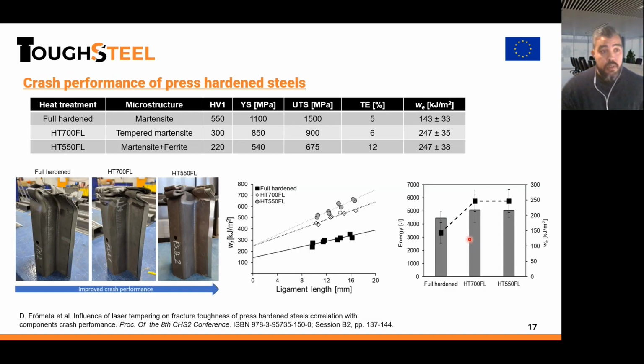Okay, here I put some examples of also a recent investigation. This is a collaboration with the STAM, where we wanted to evaluate the influence of different laser tempering conditions on the fracture and crash performance of press hardened steels. So here what we did was to evaluate again the fracture toughness by means of the essential work of fracture for different press hardened steels with different laser tempering treatments.